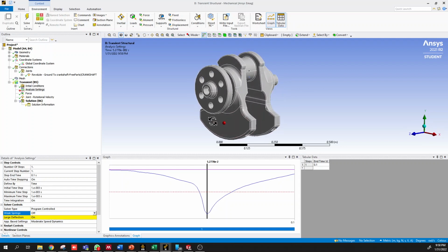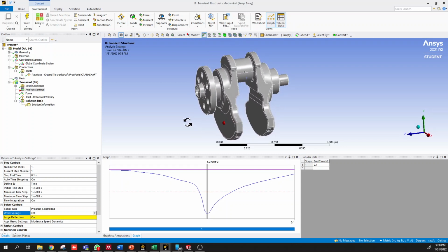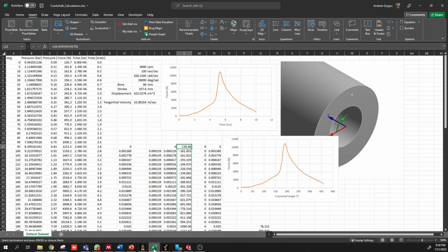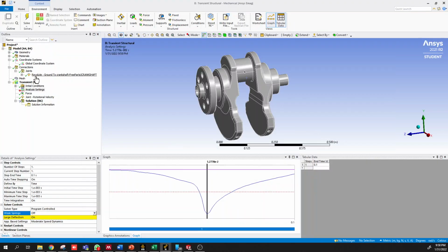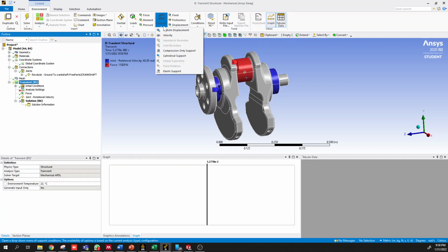One thing that I will mention is that when we go here, our temptation is to not use a joint and a connector. Some of you that are experienced with static structural analysis might have been tempted to say, instead of using a joint and a connector, I want to impose a cylindrical support here and here. We can do that for the analysis where it isn't spinning.